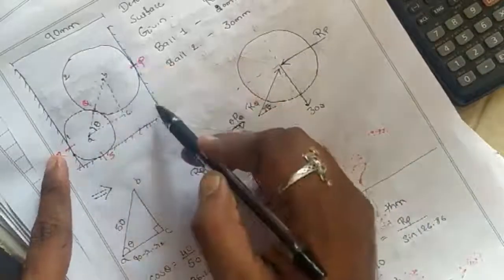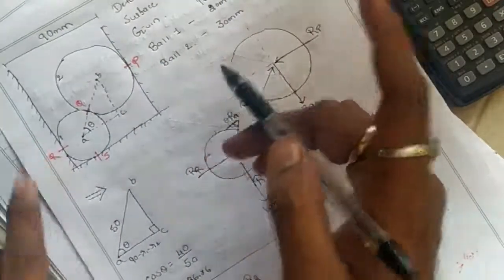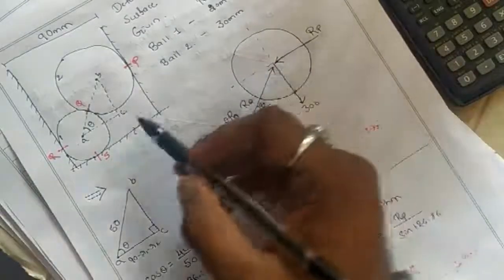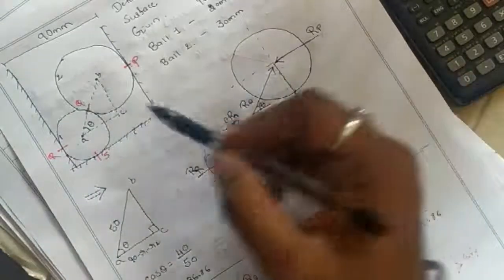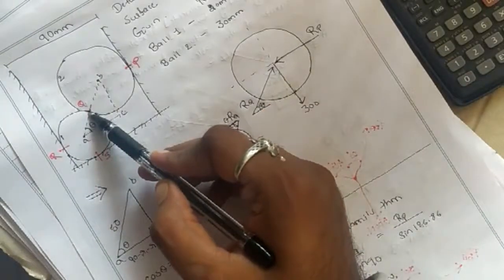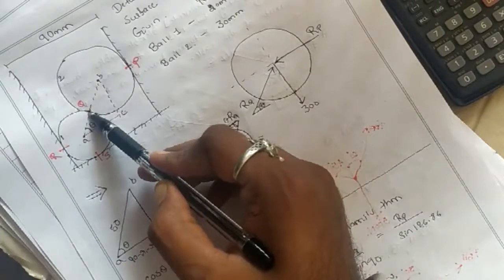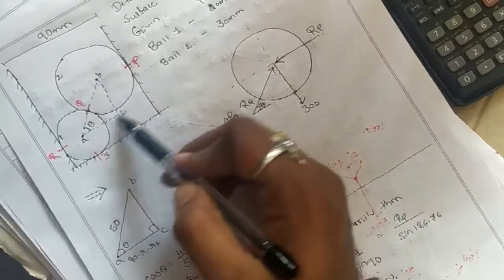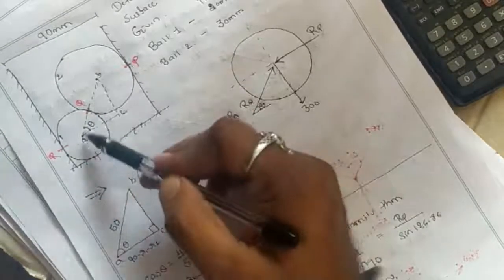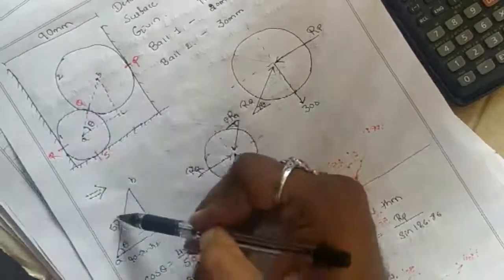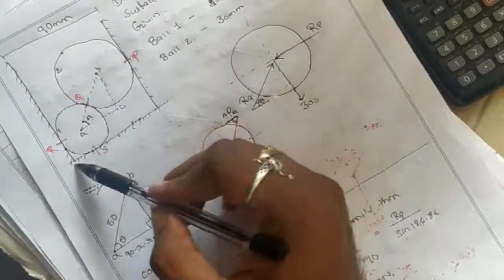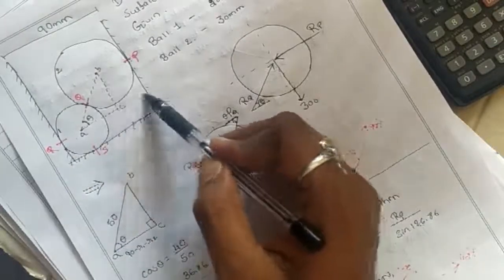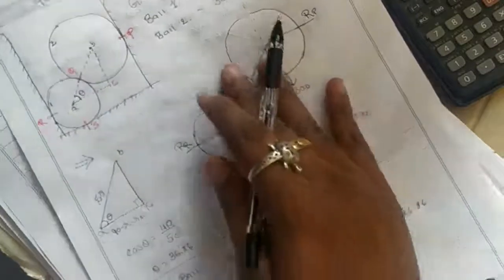Now you can see here perfectly vertical contact surface, that means perfectly horizontal normal reaction, because at every contact surface there exists a normal reaction which is perpendicular to the contact surface. So this is RP. Now similarly weight is acting downwards, and now at point Q, we don't know at what angle the RQ is acting with respect to horizontal. For that we'll join these two, and then from here we'll draw a perpendicular, and consider this triangle. Now this AB is equal to this radius plus this radius, and AC is totally 190 minus this radius of lower ball and this radius of upper ball, because this is parallel to this. So we got theta as 36.86.